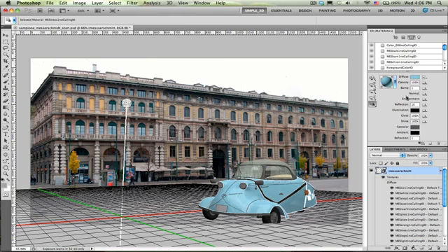And I'm going to choose the blue color here and actually give it more of a reflection. I want the car to be really reflective. We'll say 15. Choose that light here. Drop this down maybe to 6. Okay, so that looks pretty good.